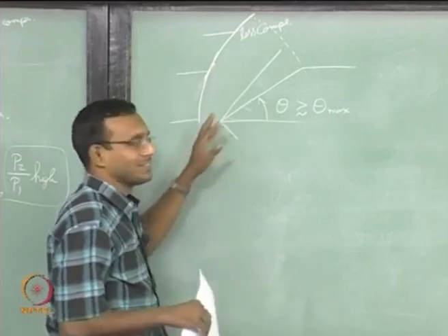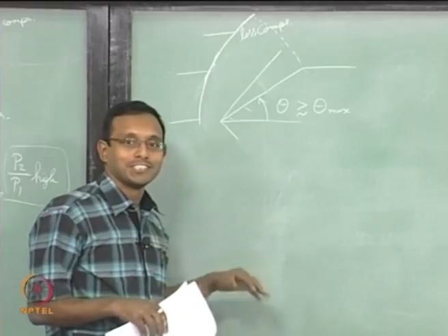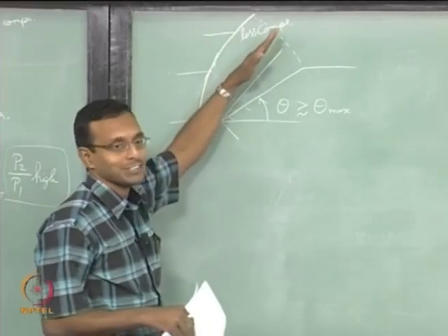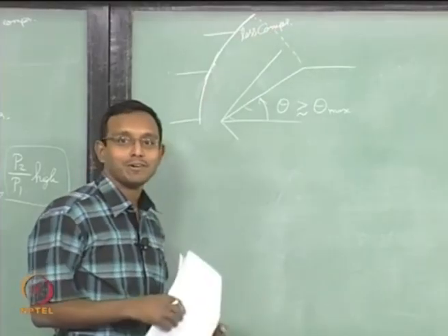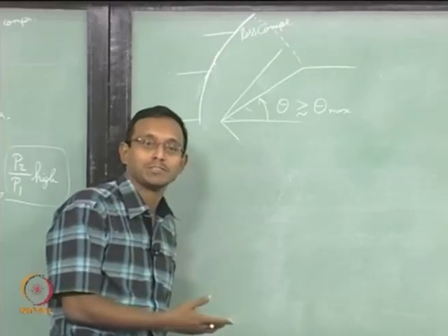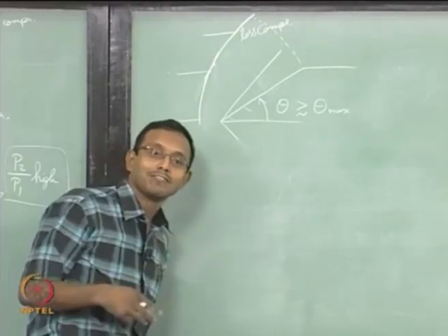And once it gets attached, there is a proof that the weak shock solution is stable. So the solution will automatically go from this curved shock to a straight line shock, we do not need to worry about that part. Okay. That proof came up only like 2 years back, it is very recent in research, we are still fresh in solving this kind of problems.